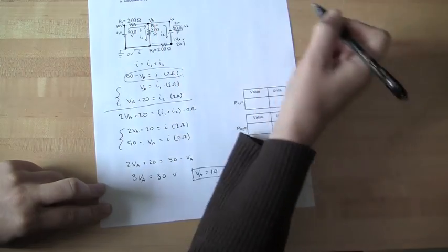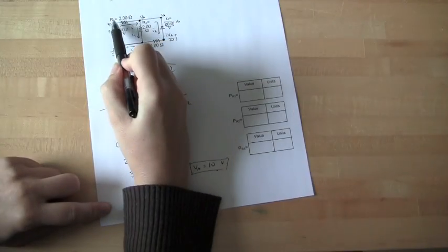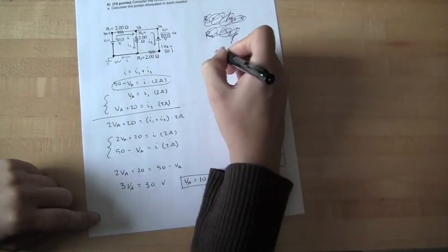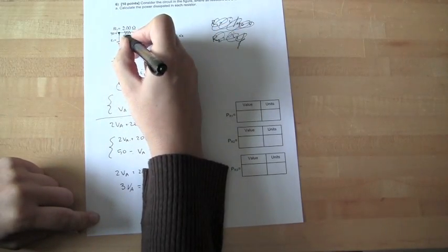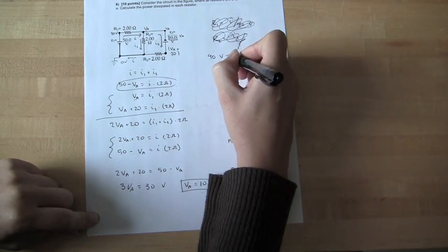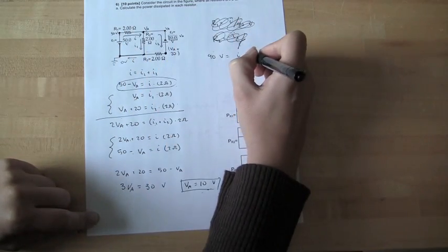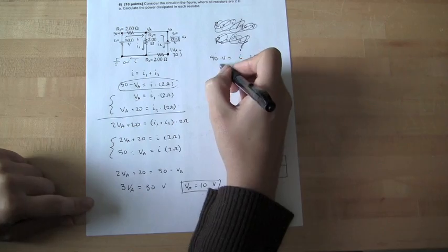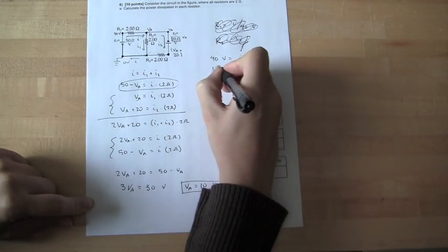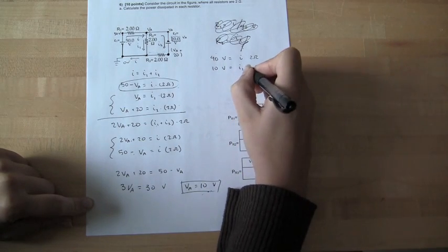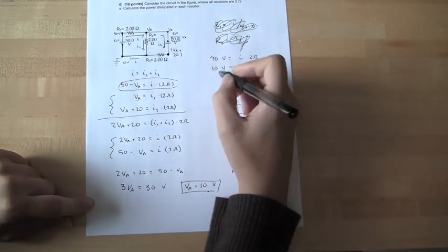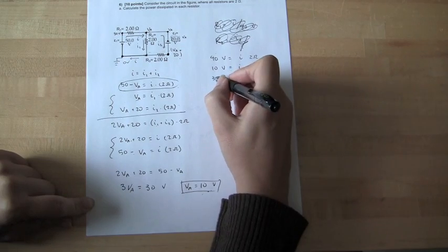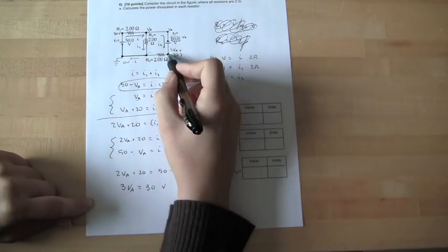So now that's the point here. Now we actually know the voltage dropped across any of these resistors. For this first resistor, we have 50 volts on one side, we have 10 volts on the other. I screwed that up. Okay, so let me start over with that. The voltage across this first resistor is 40 volts, which is equal to the current through it, I, times its resistance. For this resistor, R2, the voltage across it was just VA. So we have 10 volts across R2, and that's the current through R2 times its resistance. And for R3, we have VA plus 20 volts at this point, so 30 volts, and ground over here. So 30 volts across that resistor.